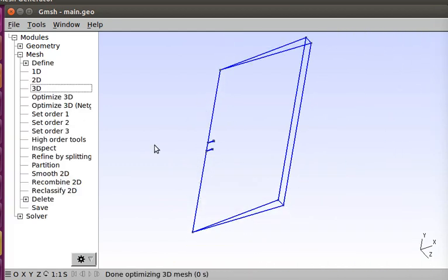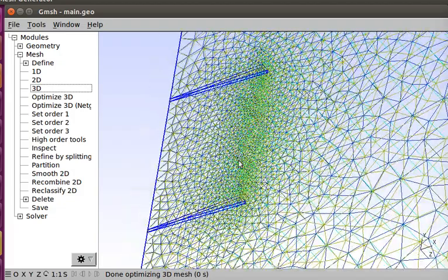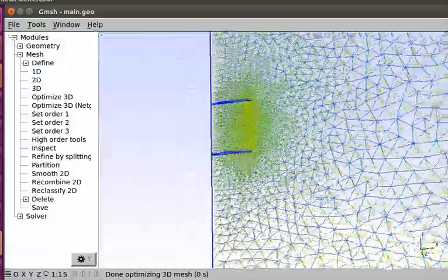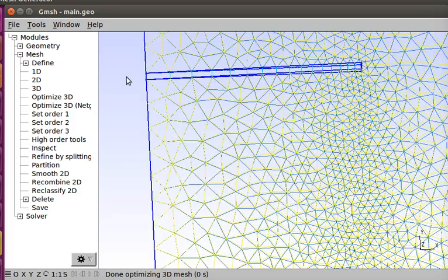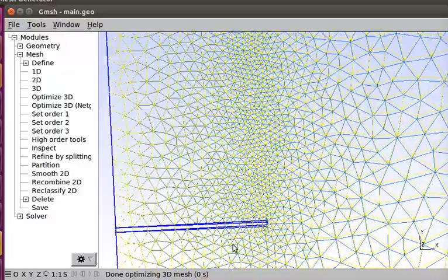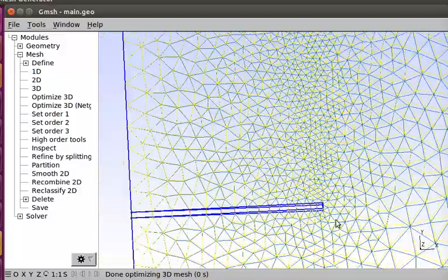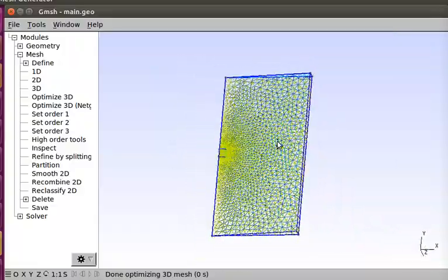We can take a look at the mesh for your edification. It's a simple unstructured mesh with a structured mesh in the cell layers, the rotor disk layers. It's a very coarse mesh, as you can see, and it runs relatively quickly. The only boundary conditions are the wedge boundary conditions in the front and back, the inlet, the outlet, and the tunnel wall.